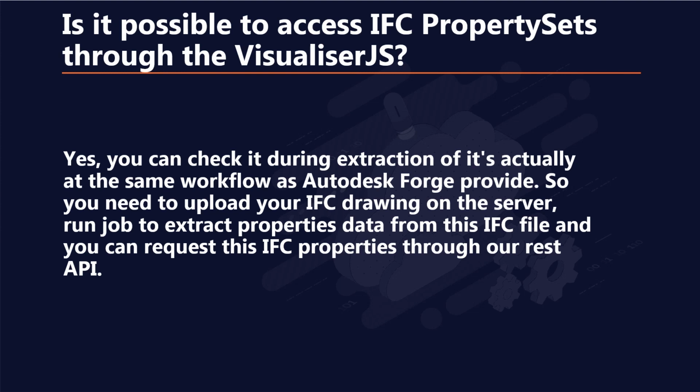You need to upload your IFC drawing to the server, run a job to extract properties data from this IFC file, and you can request these IFC properties through our REST API.